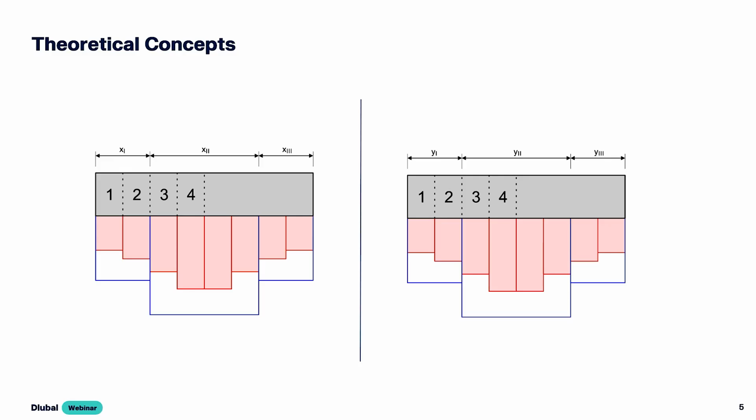And because the system is symmetrical, it is also sufficient to consider only one half with strips 1 to 4 here, for example. Strip 4 is located directly below the column, while strip 1 is located at the foundation edge. And for each strip, the required reinforcement is calculated individually. And for practical reinforcement definition, the strips are grouped into 3 reinforcement areas, defined as x1, x2, and x3, and the same in the y direction.